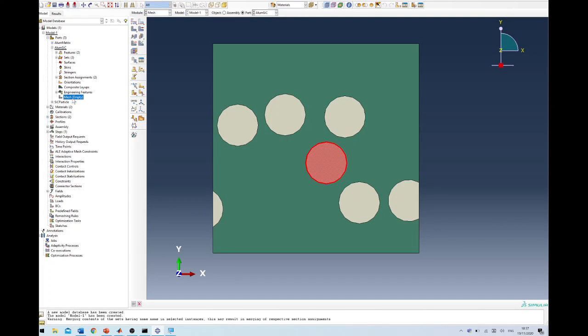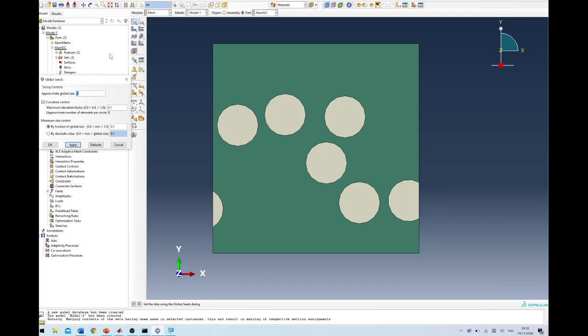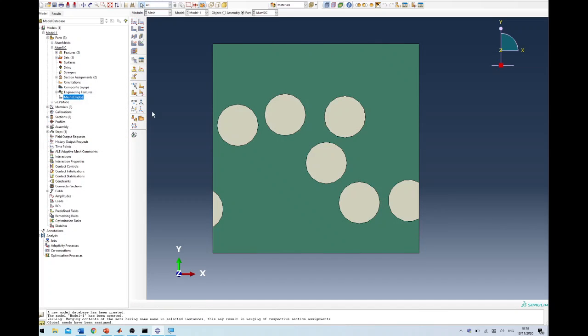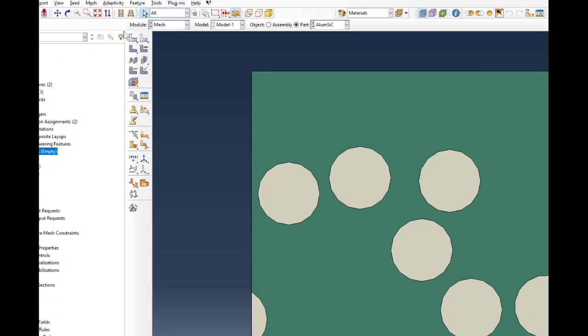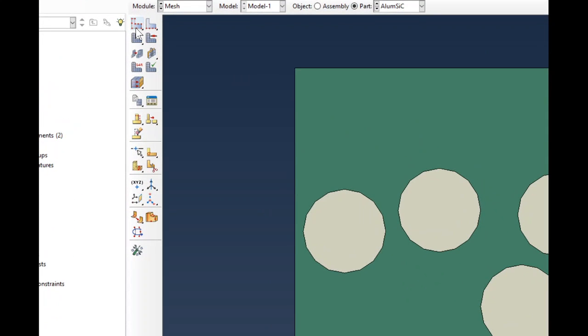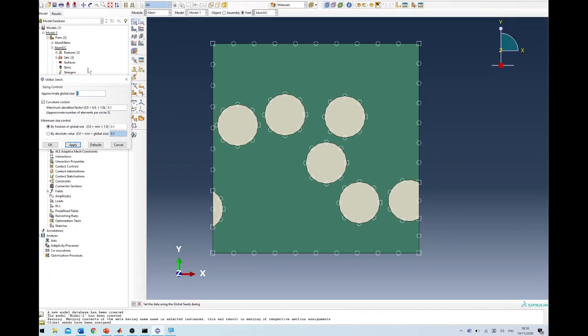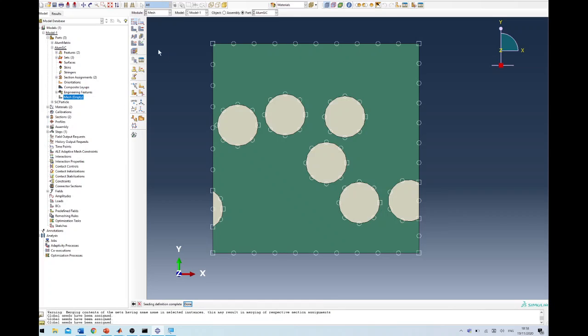Okay, so if I select here, double click there, then I can seed. It's recommending 1 as a seed size. I can start off with that. So I'll go through that again: if you go to the top here, you click on seed. It recommends a seed size. You can change it if you want, maybe 1.2 or 0.8, but it's offering us 1. Usually the defaults are fine.